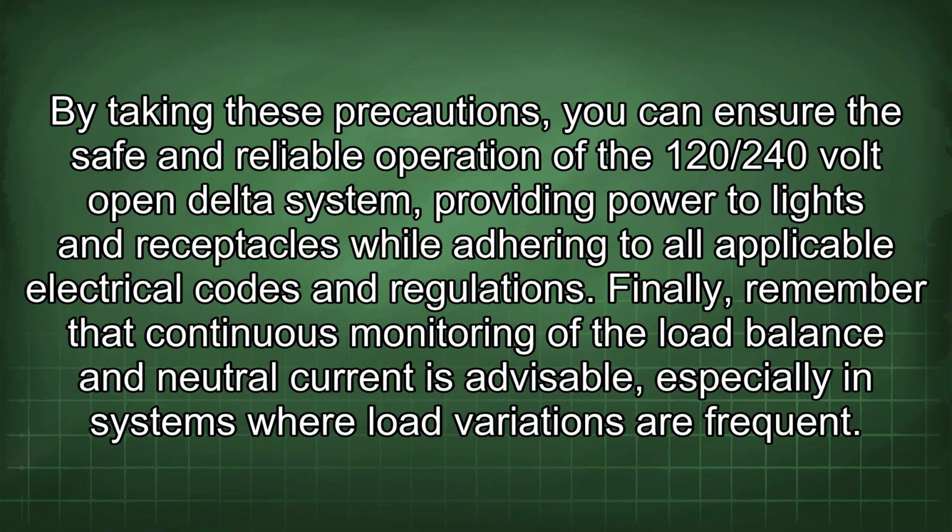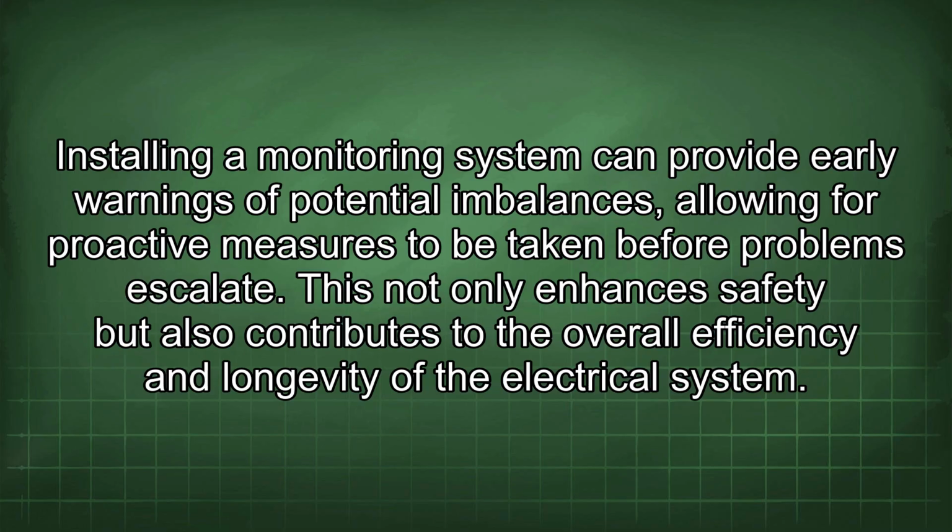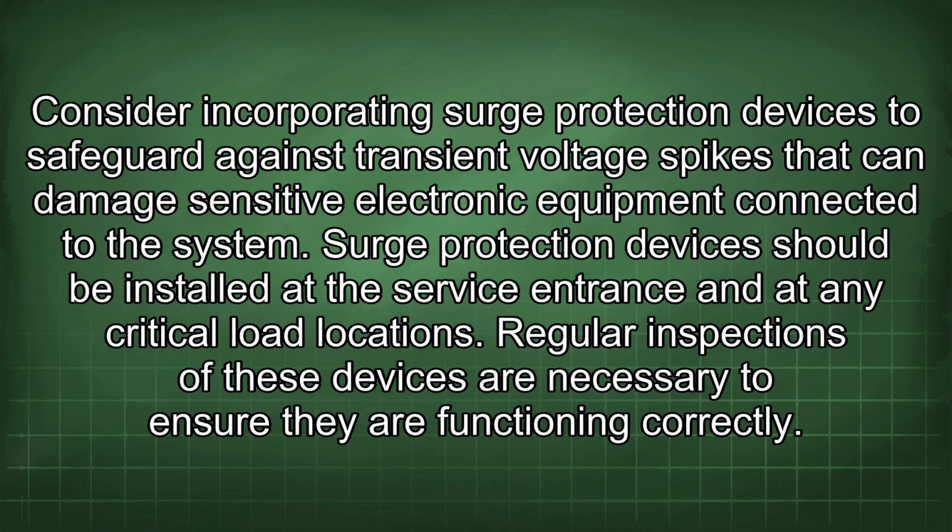Finally, remember that continuous monitoring of the load balance and neutral current is advisable, especially in systems where load variations are frequent. Installing a monitoring system can provide early warnings of potential imbalances, allowing for proactive measures to be taken before problems escalate. This not only enhances safety, but also contributes to the overall efficiency and longevity of the electrical system.